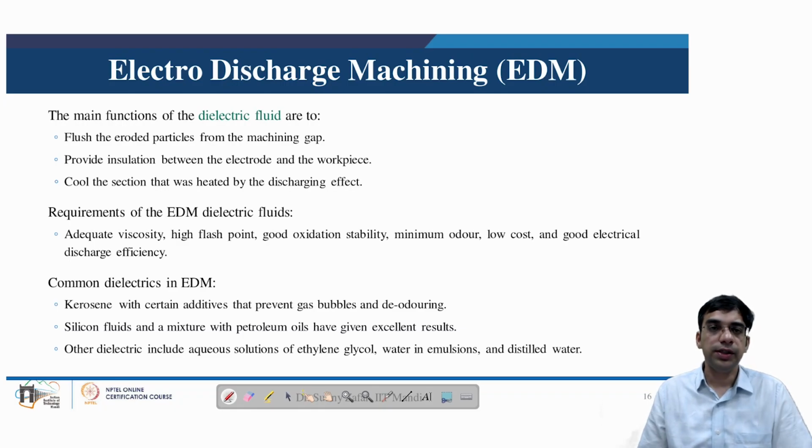So now we will also understand the various functions of dielectric fluid. Dielectric fluid plays a very important role in electric discharge machining. It helps to remove the eroded particles from the machining gap. As we can see, there is a vapor bubble which forms because of the surrounding dielectric with the spark.